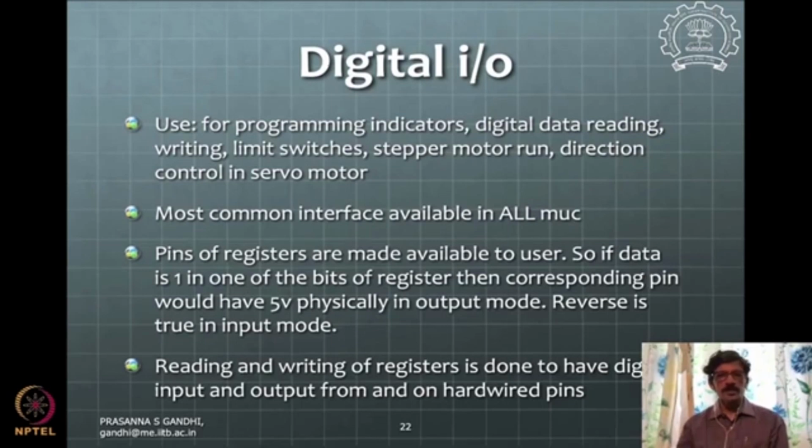Then reading and writing to this digital input output is done by using control registers, by programming control registers first, where you define whether the given register or digital input output port is used in input mode or output mode. So for that you typically need some control registers.